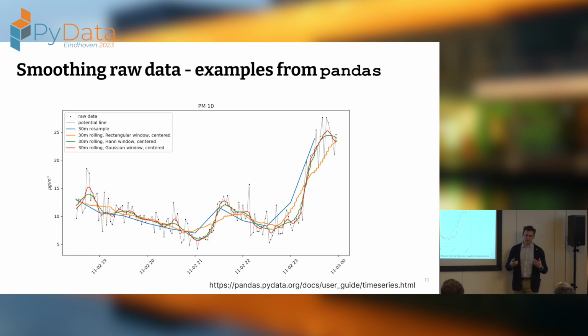Because I said to you before, particulate matter, the error is distributed Gaussian, and because of that, the right windowing function can make a huge difference when you interpret that line. So when you ignore all of that, you're removing really valuable information from the signal that you're treating. And so taking the signal out of context is something where I say, hey, please don't do that. You make your life subsequently significantly harder.